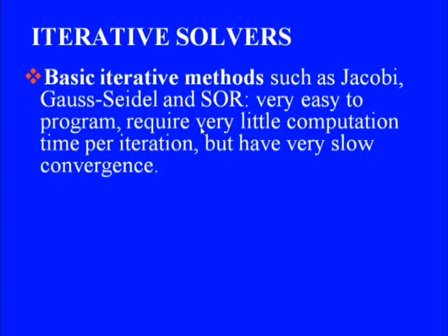So for very large systems which we have in CFD, for instance, when we want to solve the pressure Poisson equation involved in large eddy simulation or DNS of turbulent flows, where the order of the system is close to a billion, a few billions, Gauss-Seidel, Jacobi, and SOR would require many millions of iterations.